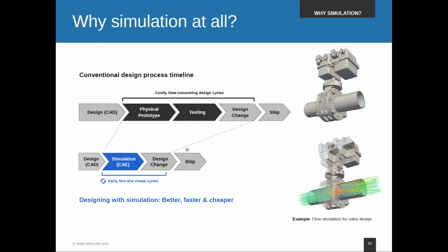To give you an example, in Formula One, which is also called the pinnacle of racing and engineering, CFD, so fluid flow simulation, plays a very important role. If they want to design a new front wing, right now they first do 100 CFD simulations of just the cross section of the wing. Then, based on the best 30 cross sections, they simulate 30 3D simulations, and then the best 10 out of them are physically tested. And so that can save time, money, and create better results.